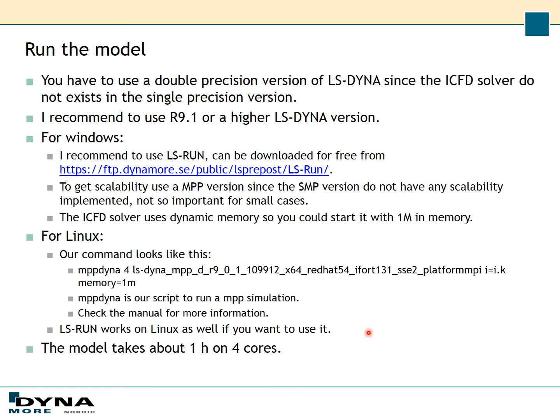You're going to run the model, use a double precision version of LS-DYNA, and I recommend to use R9.1 or a higher LS-DYNA version. And for Windows users, I recommend to use LS-Run to start your simulations, since it allows you to start both MPP and SMP calculations without using the command prompt in Windows.